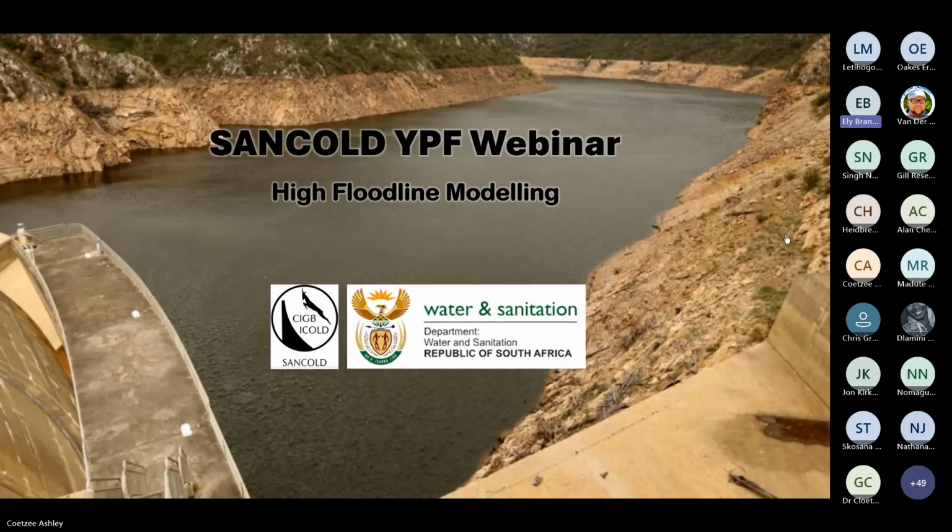Hi, Caitlin. Thank you for your question. In terms of drawing in your cross sections, the spacing between them, you want to keep the spacing between your cross sections as close as possible, because if you don't do this, you might get an unstable model. Because when HEC-RAS does the calculation, it does an interpolation between your upstream and downstream cross sections. So when your cross sections are far apart, it could have an effect on the accuracy of your results. The closer your cross sections are to each other, the better. I hope that answers your question.